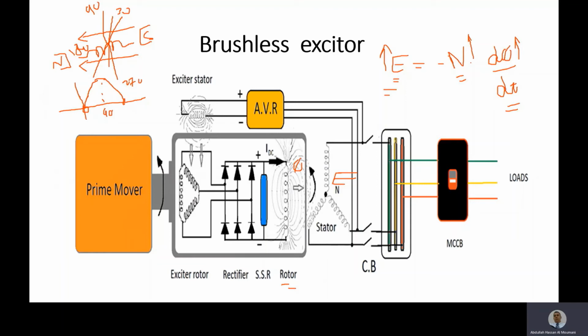It will increase, okay, but the voltage will be in the opposite direction, so it will increase like this to the maximum at 270. Then from 270 to 360, it will be reduced like this until it reaches 0 again. Okay, so in one revolution of the coil, one waveform is produced like this. This is what we call the AC waveform or signal.